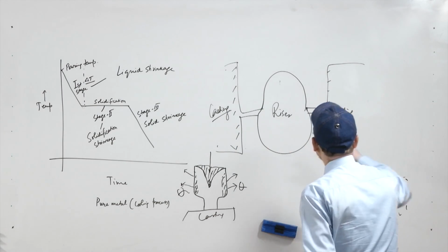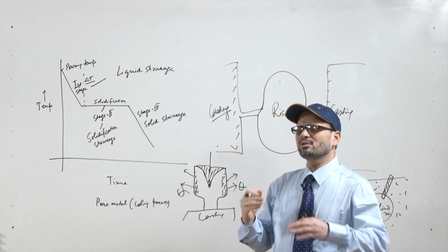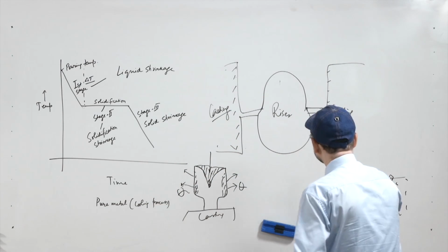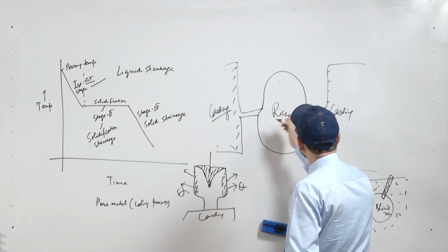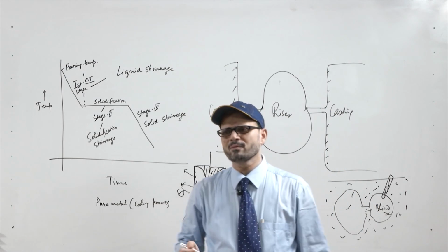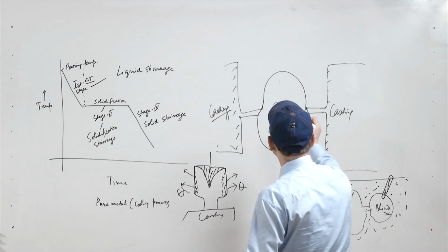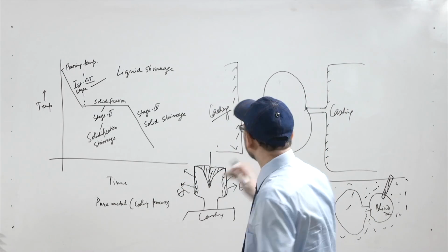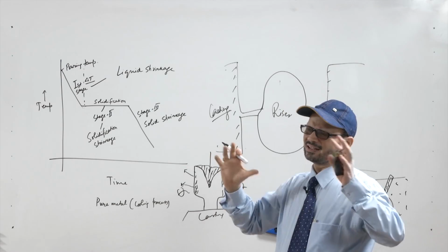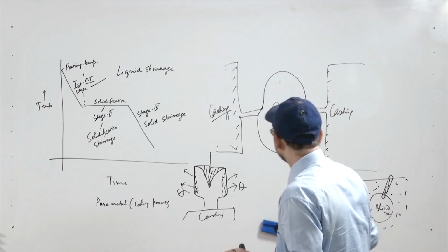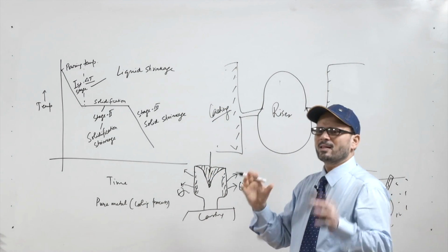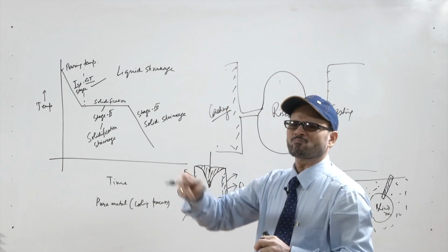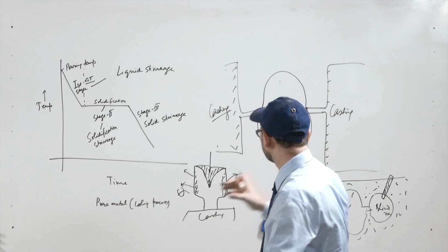Had it been a riser somewhere else, the riser would also solidify, and the riser size would have to be larger. But in this case it is getting the heat from all the sides by the casting itself, so these risers, mostly in case of circular or cylindrical castings, sometimes you keep in the middle of the casting itself.